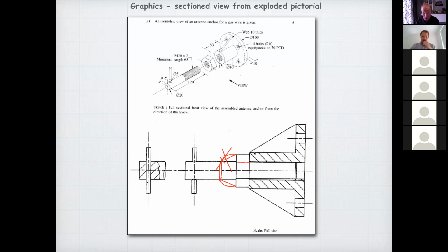See that boss there is 40 millimeters diameter, and this here across corners is 1.8D, which is 36 diameter. And as soon as you see that difference there, you know that he's got the nut correctly done.